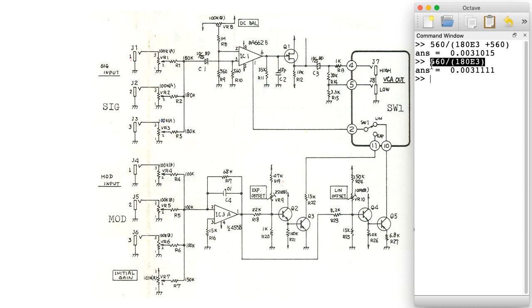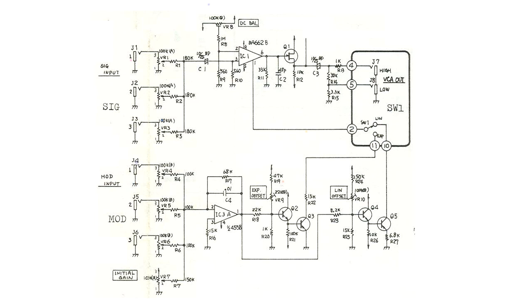This is a reasonable approximation to make when whatever error you'll get from the approximation is within the sort of variation you'll get just from the underlying tolerances of the resistors you're using. Now, I have made another assumption besides assuming that our volume pots are turned all the way up. I've assumed that we don't have anything connected to the inputs here.